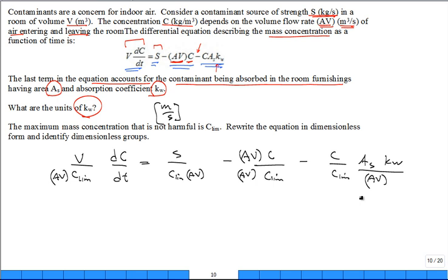I'm going to pause and walk around, and have you answer that because it's an important question. All right, so you can see that this term right here is dimensionless, and all the terms, because of the principle of dimensional homogeneity. What I did to one of the 4 terms, I did to every one of the 4 terms, true? But let's make them look dimensionless by introducing new names. We'll call C asterisk C divided by C limit.